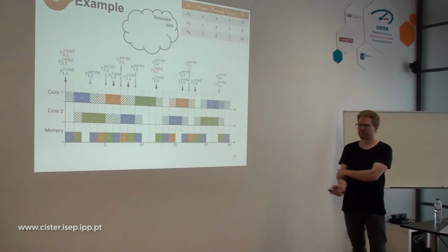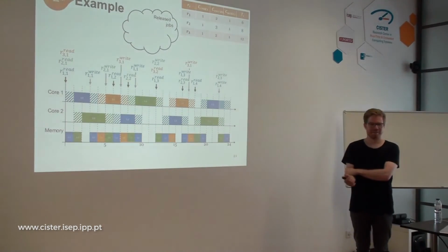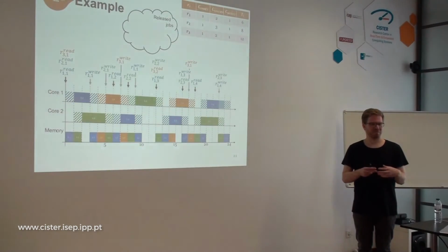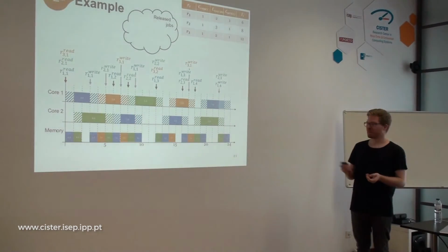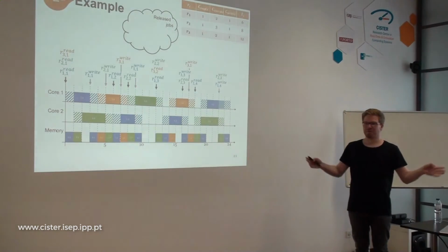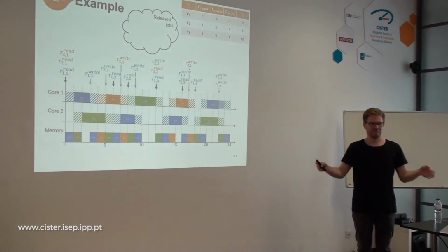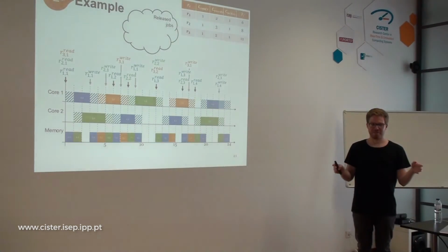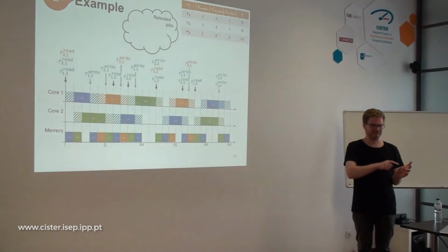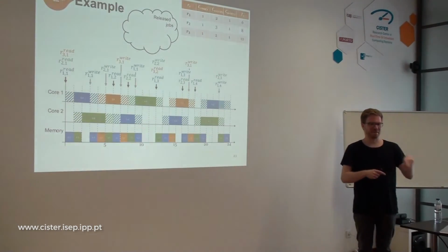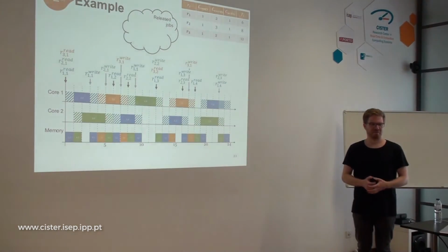Yes. Basically what you could also do is just keep the code in local memory. Because we have a distribution of periods, from 1 millisecond, which is the smallest usually in automotive, to 1000 milliseconds, which is the largest. So in my period of 1 second, I would fetch the code for the 1 millisecond runnable 1000 times from off-chip. If I keep it in my local memory, then I get a lot of performance just because I shrink this memory access time a lot.